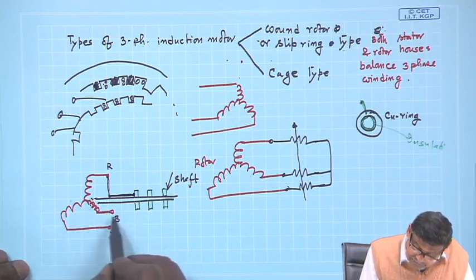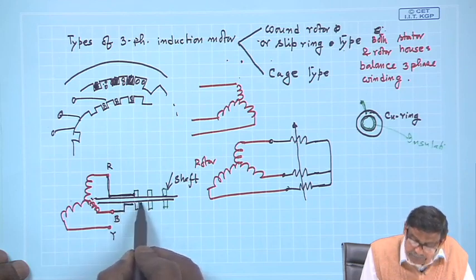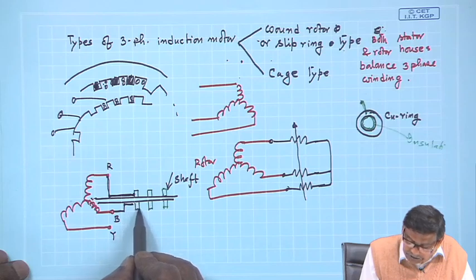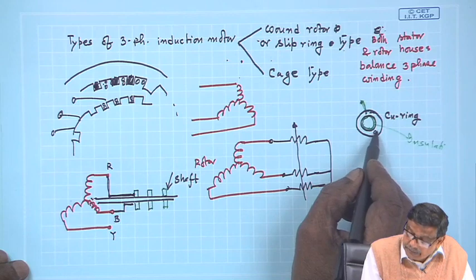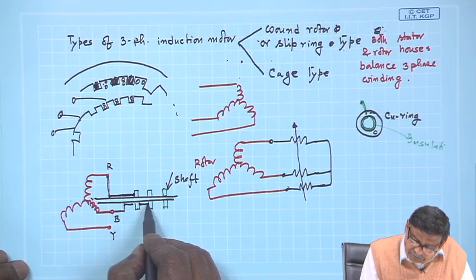Similarly, you take another piece of wire from this fellow and run it along the shaft. Soon you get obstructed by this first ring, so make a hole in that ring and push that wire through, insulated. I mean you have got the idea, and you terminate it to the second one.